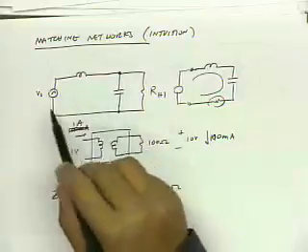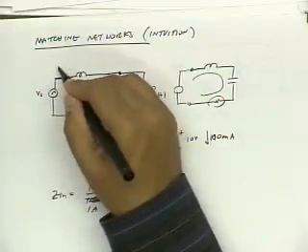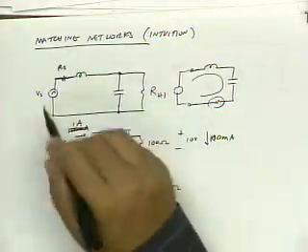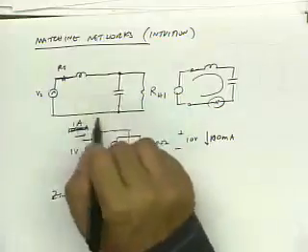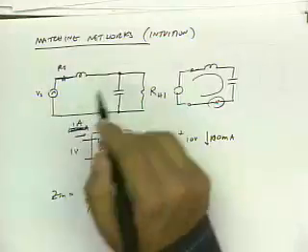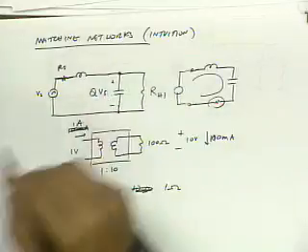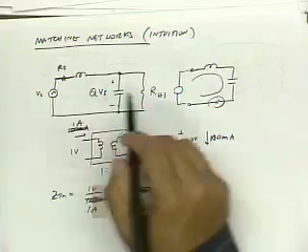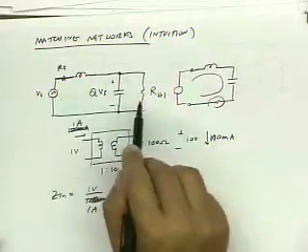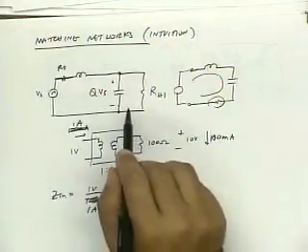In this circuit, if I drive this with some source resistance Rs, then at resonance, if this is designed to be a matched circuit, the current is just Vs over 2Rs, right? But the voltage across the reactances is Q times Vs. And that means that because I have a voltage multiplication, I have the same current multiplication in the other direction.